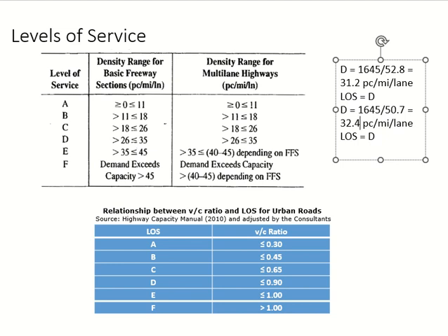Okay. But what happened? What was the effect of weather? Reduce the free flow speed. Okay. So free flow speed was 52, now it's 50 something. Another thing is it increased the density. Yes. The value of density has increased. It did not go above the threshold, but there is an increase. Okay. So because of the weather, people are going much slower, taking more care with the free flow speed. And in the peak hour, their spacing is now much closer to each other. Yes, they are now closer to each other. Density is more. Okay, so yes, there is an effect on free flow speed.